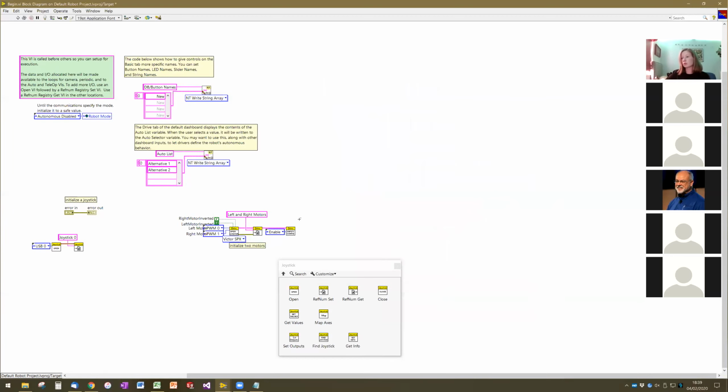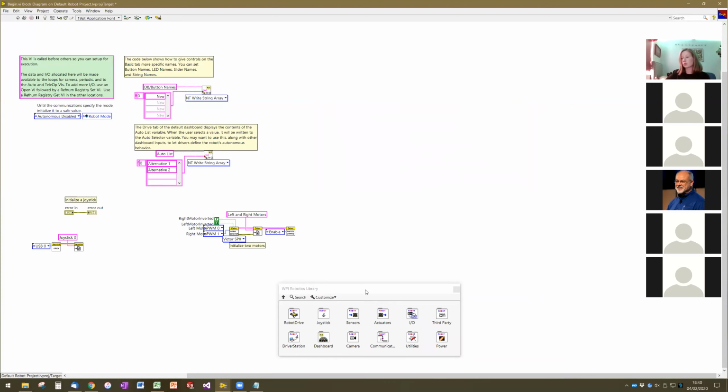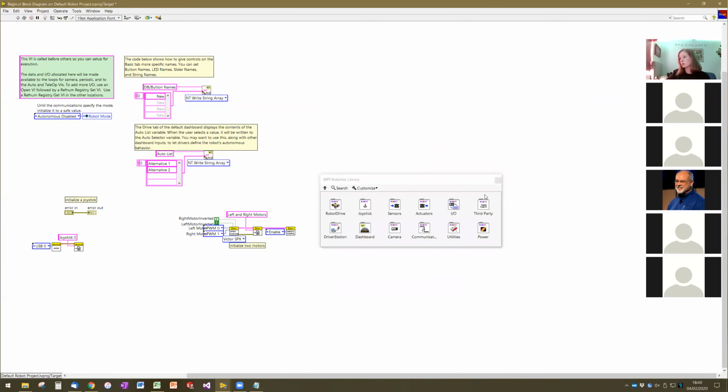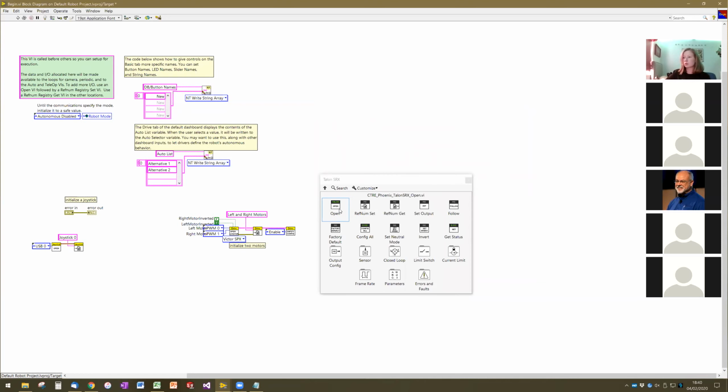One of the other things that you can do while you're opening devices is configure them to do different things. So if we look at a more complicated open statement, like if we went to the open statement for a Talon SRX, we would have an open. In this case, this requires that we go to the CAN bus. So the ID number here is the CAN ID.